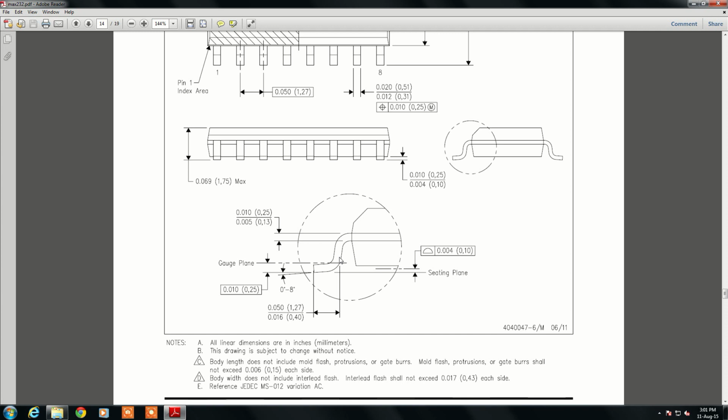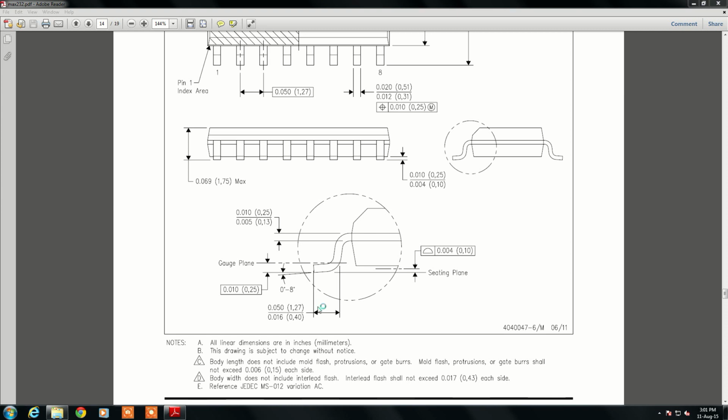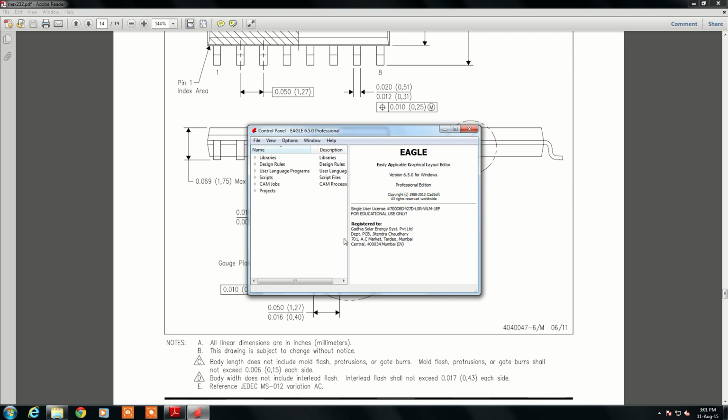For this tutorial we are using a software which is Eagle software. Whenever you use this software, there are three things. One, creation of a circuit diagram. Second, creation of a layout. Third, creation of Gerber files. These are the three steps for any project or product to be implemented. So first let us see how to create a circuit diagram. Go to File, New, then Schematic.